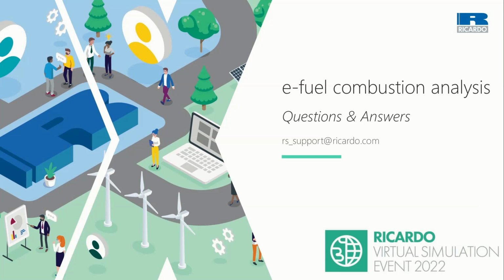However, this type of simulation is computationally very demanding and previously could not be easily integrated within a virtual product development process. In this workshop, we have illustrated a novel workflow building on the strength of the Ricardo software 3D toolchain VECTIS that allows for a fast and accurate simulation of the fuel composition effects on the power and emissions profile of a powertrain. By leveraging the use of a lower fidelity modeling framework, the CPV, to reduce the overall computational cost of the very accurate R2DK framework, it becomes feasible to integrate detailed kinetic simulation in a virtual product development process, where it can be used to inform the development of 1D models.